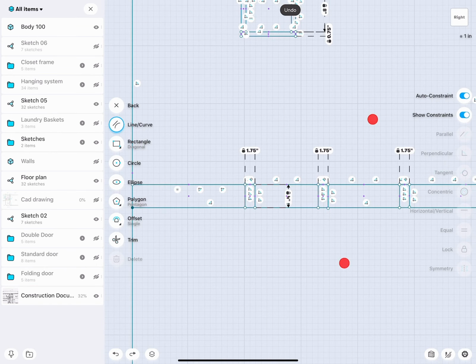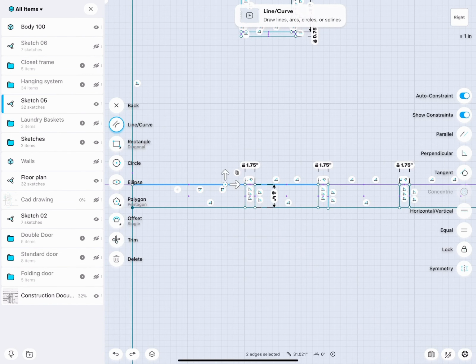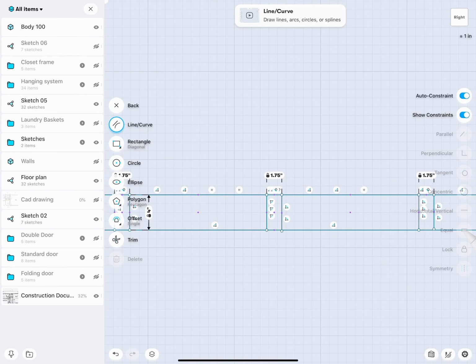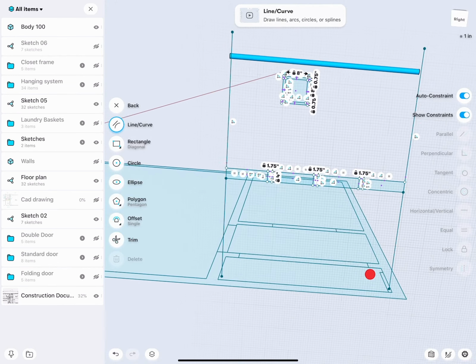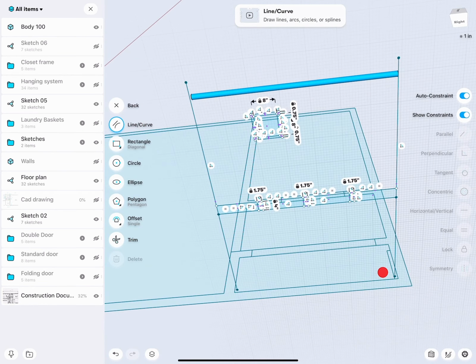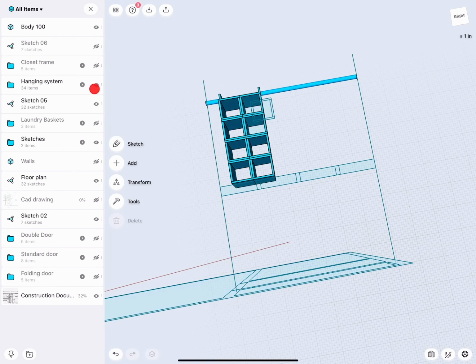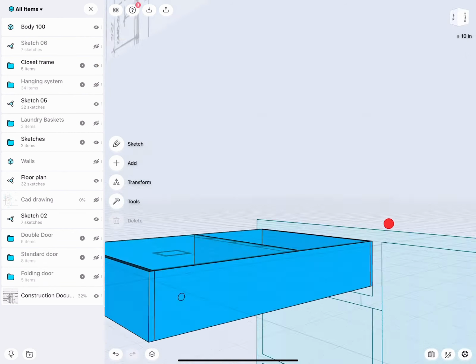Pretty nice, no? And then U and U could also be equal. So very easy now. I repositioned those vertical slabs. So what happens now if I say, well, what about U and U are equal, and then U and U are equal? Zip. You see, perfectly everything got subdivided. So that's the reason why this was easier to do via the sketch than via the scale, because the sketch solver can perfectly subdivide the spaces just by using the equal command.